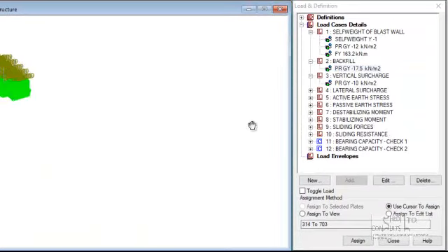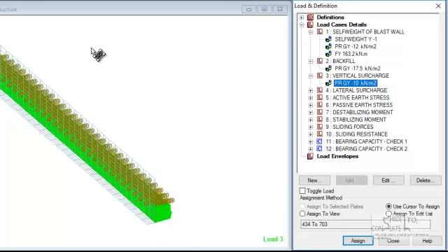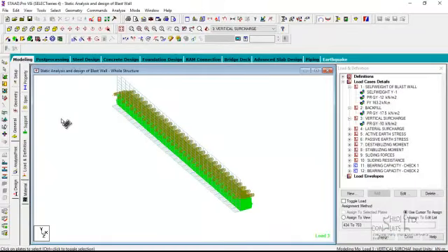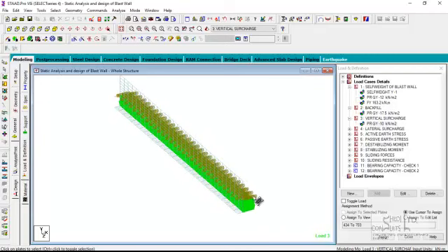Okay, so we also have the vertical surcharge. Because you have your pigging equipment on this side, this wall is separating this pigging area from the other side of the process facility. So you have surcharge loads. The minimum surcharge load as provided for by the code was taken as 10 kilonewtons per meter square, and was applied on this side as a result of imposed load, movement, vehicles, and all of that. So that surcharge load was catered for. This is live surcharge, and it was applied on the structure.